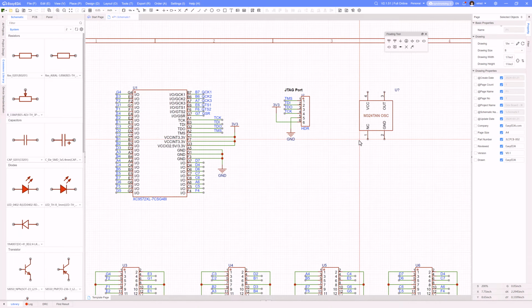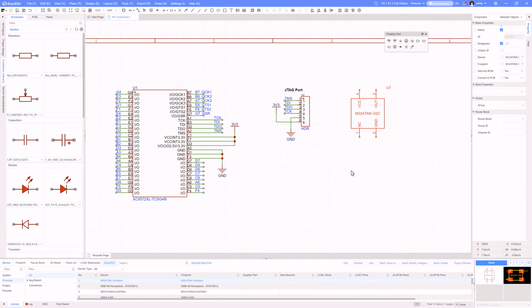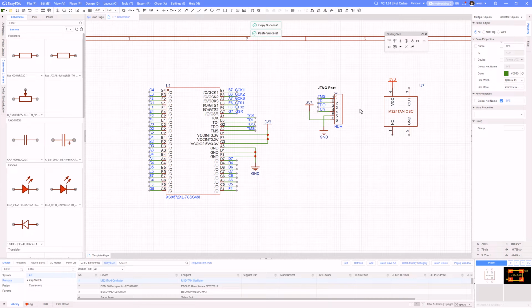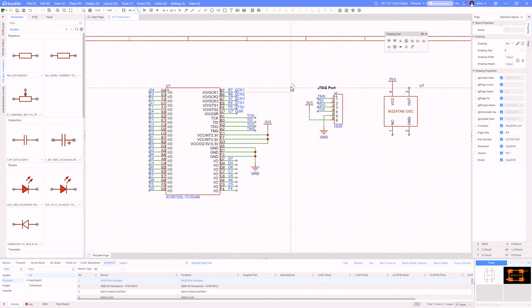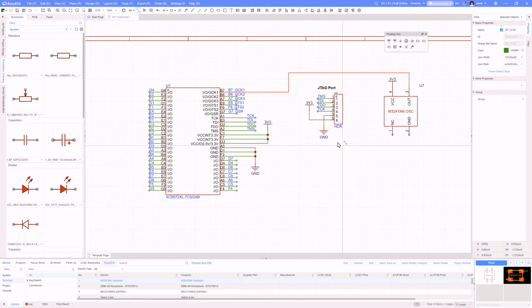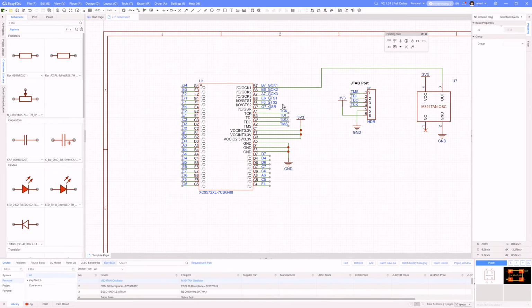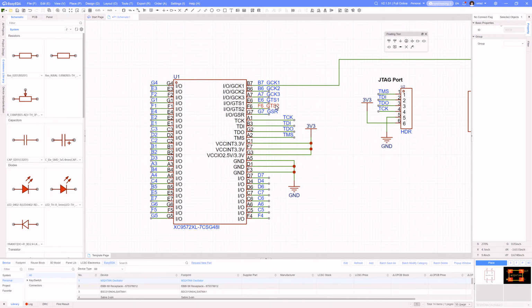and just choose that I want to set it over here. And it's going to need VCC, and in my case, again, that's going to be my 3-volt. It's going to need an output, which is where I'm going to send the clock out to. And I think I'm going to run that clock over into this pin here. I will need a ground and then a no connect, and that's just this X that says I don't want to connect anything to that pin. Then I have left 1, 2, 3, 4, 5. You know, what are these 5 for?